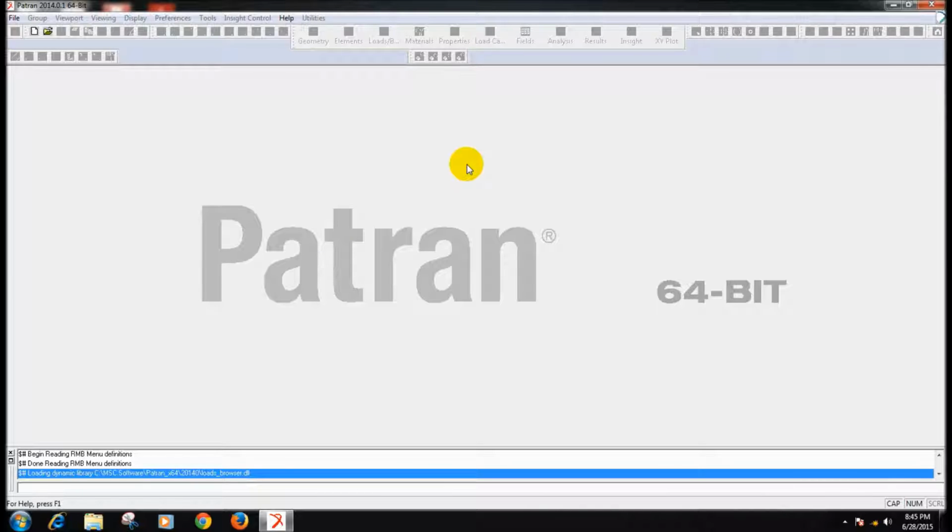So in these particular areas, plate with a hole problems, when subjected to quite a high load, at the area of discontinuity, that is the hole inside the plate, you can find that very high stress concentration is seen in the vicinity of a discontinuity in a plate. So we are very eager to capture such things, since the application is mostly in mechanical, aerospace and automobile